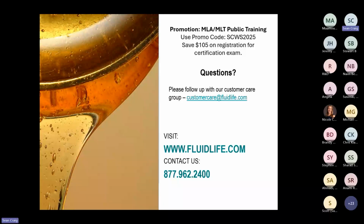When it comes to very common gearbox, hydraulic systems, compressors, whatever it may be, the best sampling practice for those is, at a minimum, take it from the reservoir, take it when the oil's warm, but the best way is usually when the system is running, and that is using sampling hardware, minimess valves. And not every case is going to be the same. So the hardware exists to tackle most situations, but if it's something you're interested in, feel free to reach out to us. We can assist you in obtaining that hardware. Take some pictures of the unit, say what should I do here, send that over to us, and we can assist you.